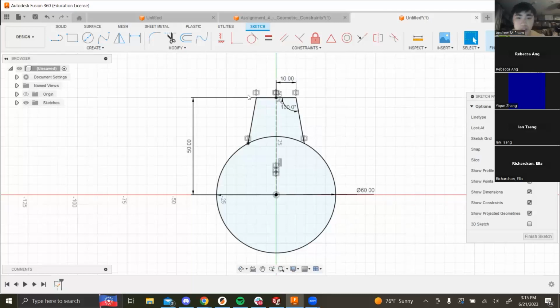To me, this tooth looks a little bit big, right? So you can go back and edit all these constraints. Let's say I wanted this to be 7 millimeters instead of 10. Now it's skinnier, right? Or if I wanted a more aggressive angle or a more shallow angle, depending on how you see it, you can change this. So now we have one tooth.